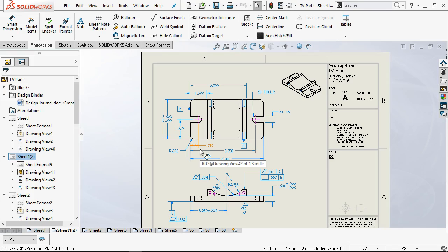All right, so take into consideration what the function of that geometry is doing before we go in and start applying a lot of GD&T and start applying a lot of those four decimal place dimensions. It comes back to use some common sense. All right, if I'm manufacturing this, if I was building this, what would I reasonably be able to hold as far as a tolerance, and then what is the special case that, yes, I'm going to have to take it to grinding, yes, I'm going to have to take it to EDM, I have to take it to another process to get to that tolerance and ensure that I have that precision. Okay.